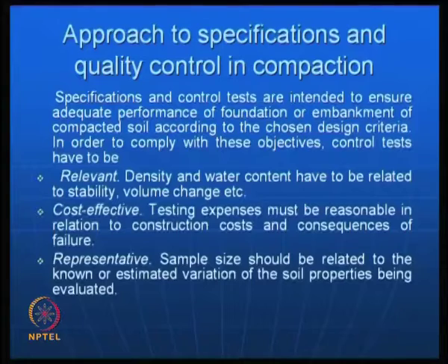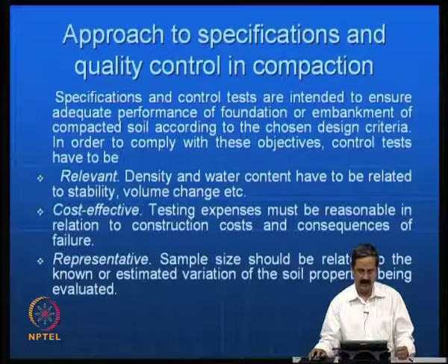Today we would like to see how we specify these specifications, and also what we mean by quality control in compaction. We would like to see some of these aspects. Specifications and control tests are required to ensure that you get adequate performance of the foundation or the embankment of the compacted soil according to the chosen criteria.